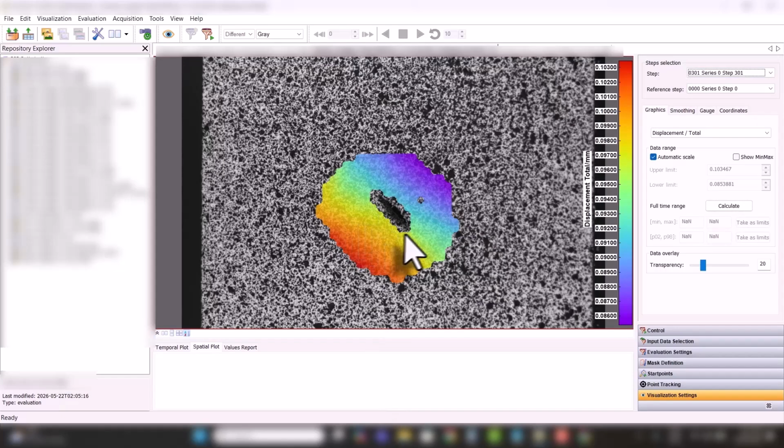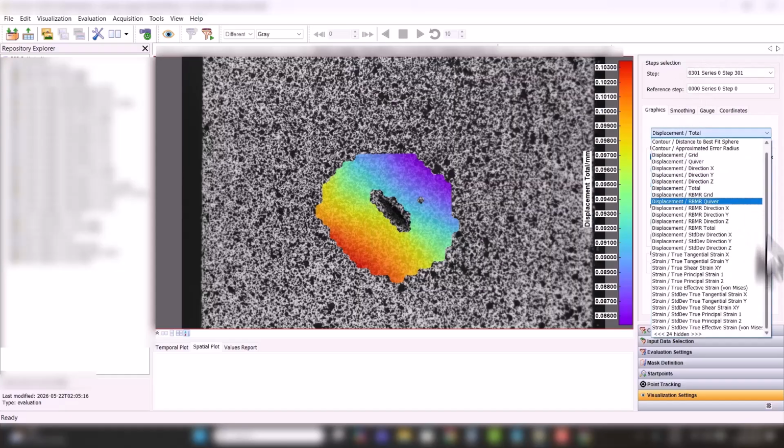So yeah, we can see we've definitely refined the correlation. We're hugging the notch even more, and it's going to be harder to correlate at the notch tip because you're going to have speckle pattern breakdown here. There's going to be yielding, really necking here, material that's past ultimate strength at the tip. But let's see.